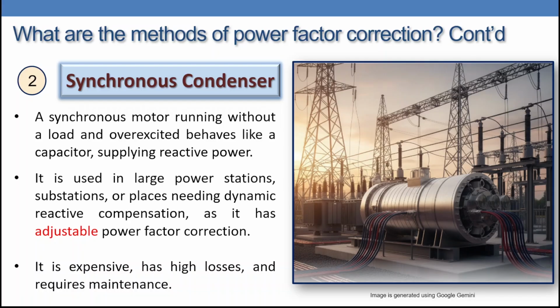It is used in large power stations and places needing dynamic reactive compensation. It has adjustable power factor correction. So compared to the previous case, that one is adjustable, while the capacitor bank is a fixed value.